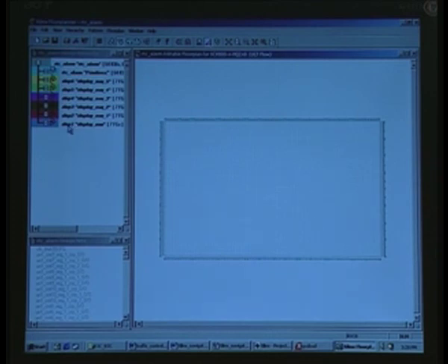Suppose there are some displays on that, what you have already seen in the IO card that we have used earlier, and which is right there here, and suppose this is display 1. Suppose you want to get this here, what you can do is just hold that, click on the mouse and then hold it without releasing it and get it into this area.